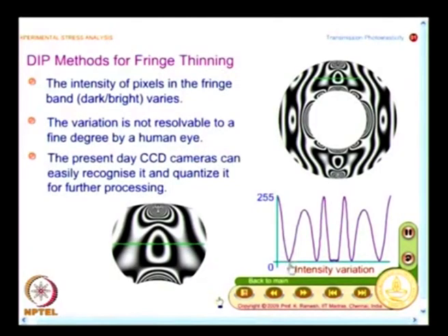On the other hand, when I go and look at the intensity values recorded, I may have to do time averaging, and then you want to eliminate electrical noise. So, you take several images in a short time and then take a time averaging. When you do that kind of image recording, and when you look at the intensity variation, you get an intensity variation like this.